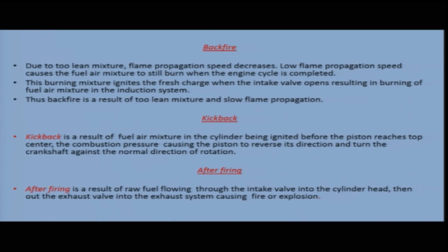And afterfiring is a result of raw fuel going through the intake valve into the cylinder head. Now, the fuel is flowing from the intake valve into the cylinder head and then goes to the exhaust valve into the exhaust system and causes fire or explosion. So, fuel coming from the intake valve into the cylinder head and into the exhaust system causes fire or explosion. So, we have seen backfiring, afterfiring and kickback.